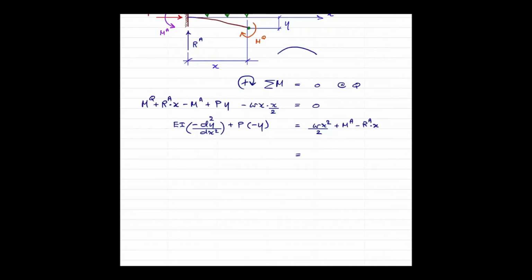You don't get the real ductilities of the structure. You change the detailing in the reinforcement, you change the ductility, you change the failure mode. So it is important to conduct physical specimen testing.